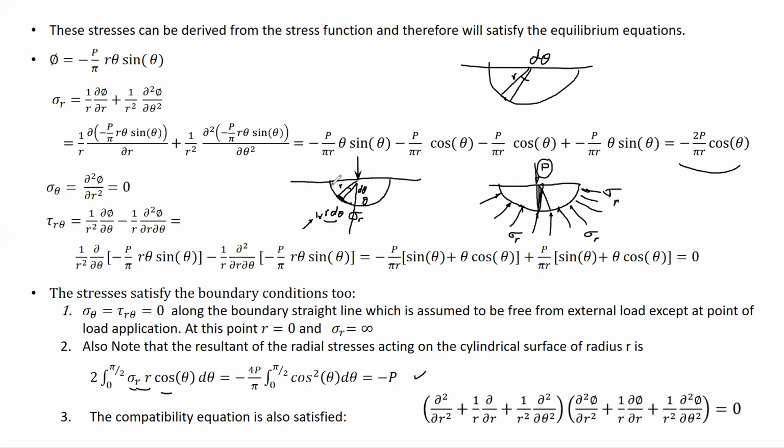If I integrate from the beginning of this semi-cylinder to the end, it gives the total force in the vertical direction, and it is shown to be minus P. Why is the upper bound only half of the semicircle? I have a semi-infinite body where the load is applied here. That's the beginning, right? So I'm cutting half a circle from that body. It would be separated, right?